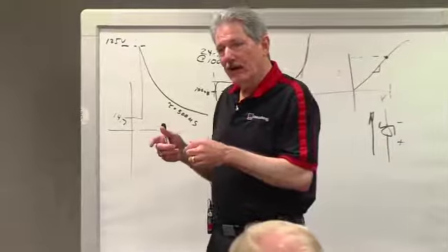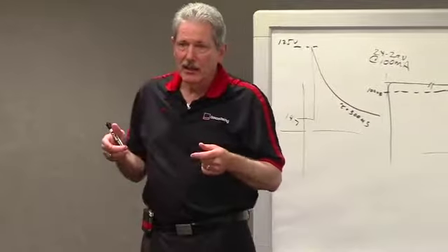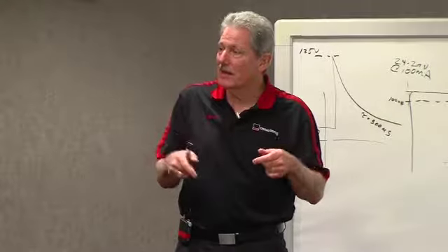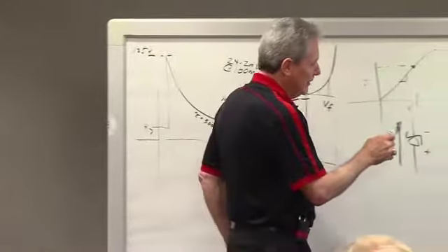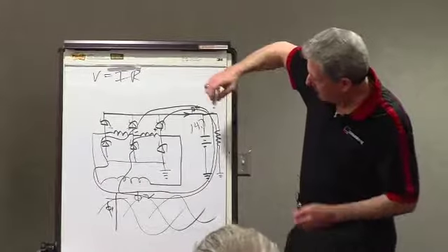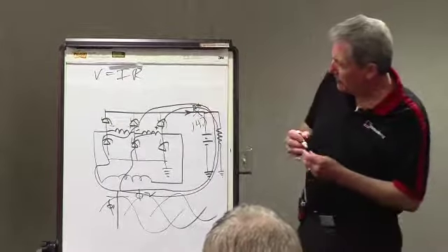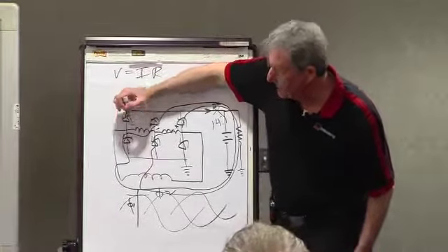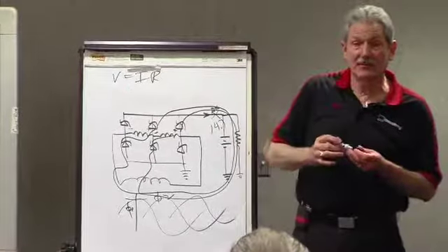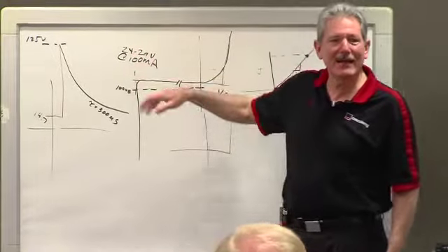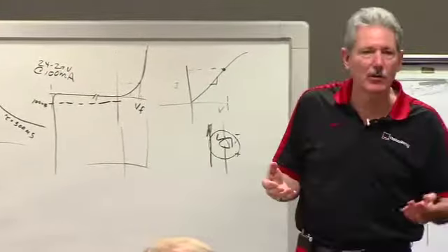Okay, in 1985, with the 9SI CS130, Remy introduced an alternator with centralized load dump protection, where instead of using standard diodes, they use these. Okay, so let's go back here to this. As soon as I open this, the voltage is going to run up. But as soon as the voltage runs up, it's going to hit this Zener, and it's going to clamp it. So it's going to go out to 24 to 29 volts. In actual practice, it's 30, 31 volts.